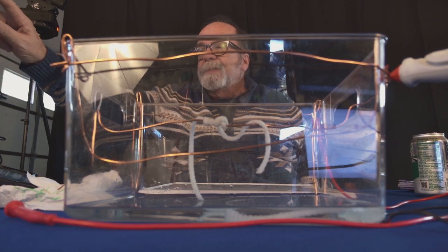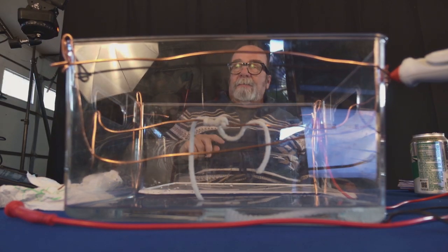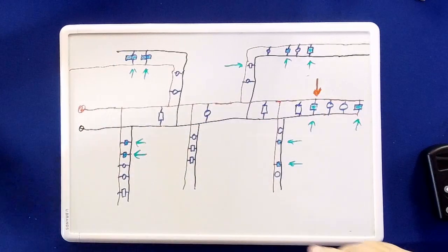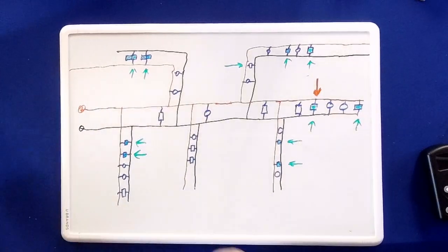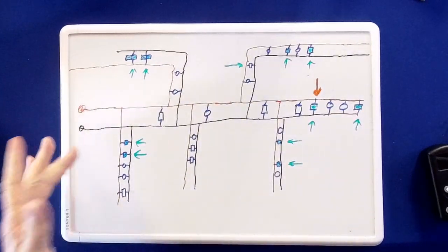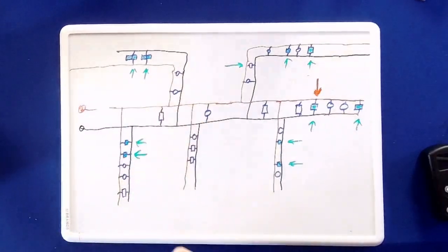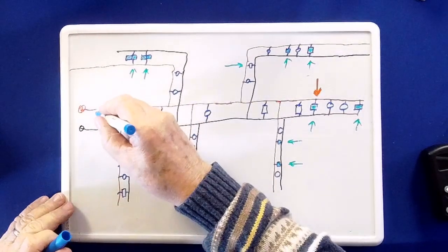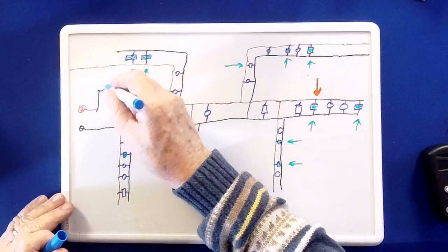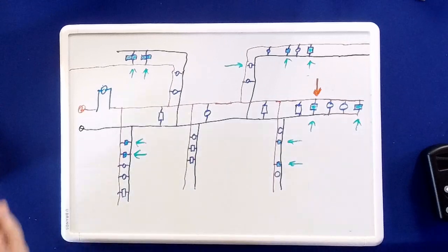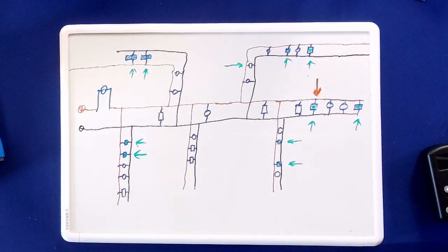So you want to put this logging meter up here on the head end first, and you want to do it hot on the SLC. So leave your SLC hooked up. Break one side of your circuit and put that logging meter in series with the circuit so you can watch what it's doing.